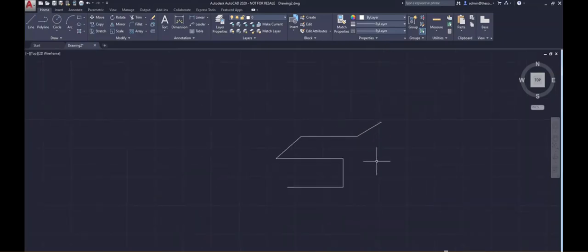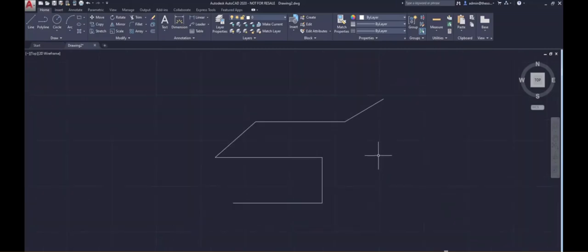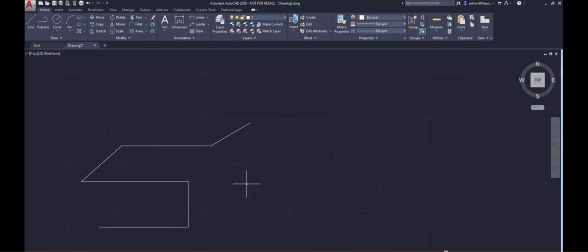Now in this case, I specified the angle right here using the line command, but there is an option that can help you do this pretty easily as well. So for that, I'll once again go to line tool, and now on the status bar, I have this option here called polar tracking. Now this polar tracking will help you specify any angle that you want. So I'm going to now click on this arrow which is right next to polar tracking, and the angle currently set is 90 degrees.